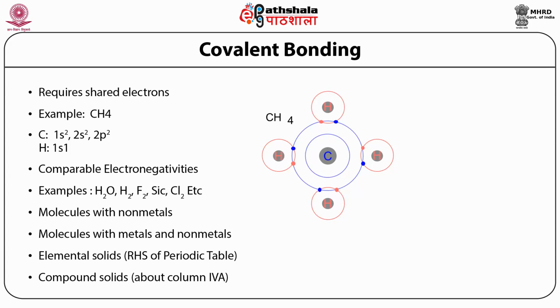Covalent bonding. In this bonding, atoms share their outer shell unpaired electrons, leading to a stronger and directional bonding, which is shown in this figure. An overlapping of orbitals is required for lowering of potential energy, which is typically facilitated by vacant spaces in the outermost orbital of bonding atoms. Typically, overlapping orbitals are directionally oriented, which further gets compounded by hybridization between overlapping orbitals, imparting a strongly directional character to covalent bonds.